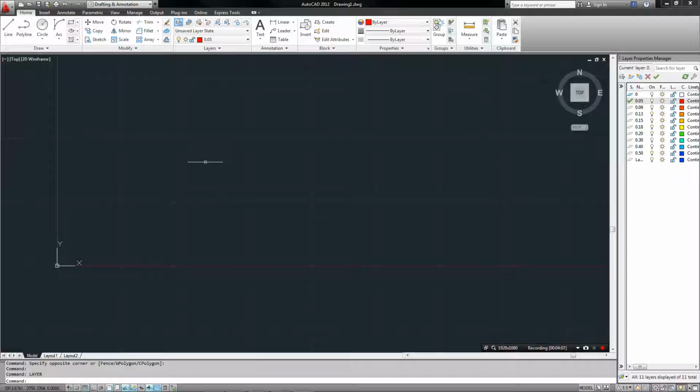Awesome. Okay, let's have a go at some of the commands that we've been given in the booklet. So line, very self-explanatory. L, line, and I draw a line on the sheet. There's my line. Press space to end the command, and then we're done. As Shane's mentioned, it's really important to just keep your left hand for commands by using the letter commands, and then keep your right hand on the mouse, depending whether you're right or left-handed, and that'll make life really easy for you.